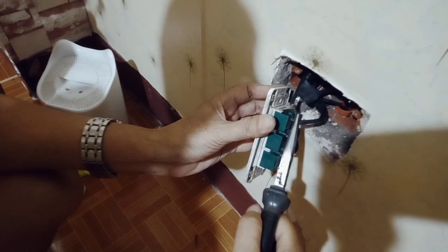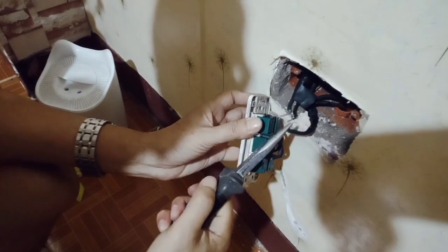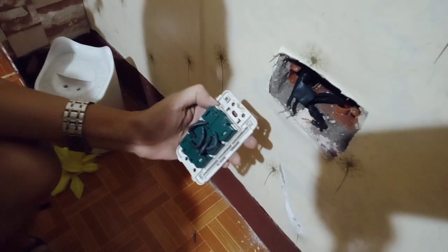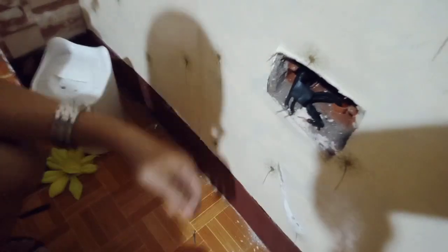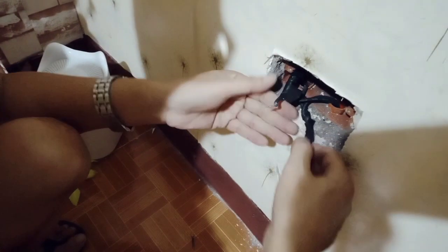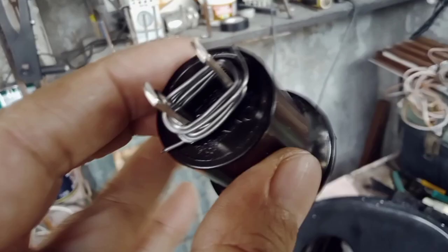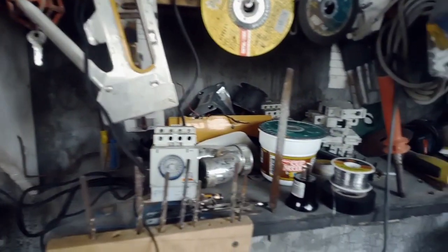After I remove the defective device, I'm gonna make my final test on each loop for open and short circuit test before switching back to power. In this method, I'm going to use a shorting lead to be plugged in at every point in each loop. This method can be performed in several ways, whichever is convenient for you.